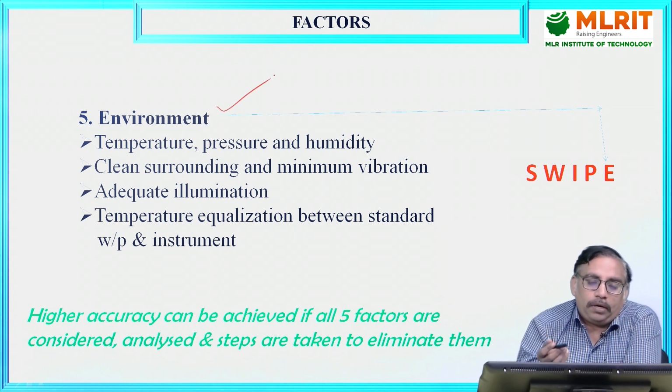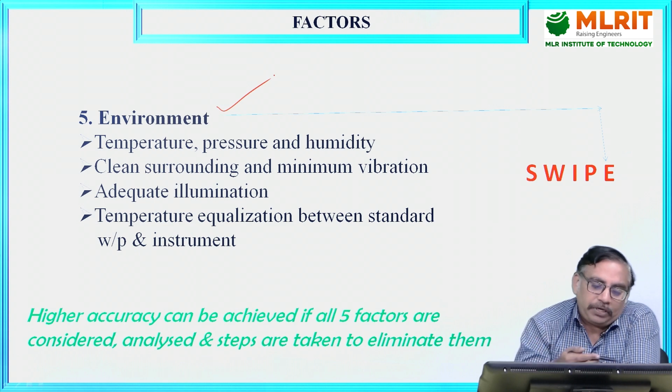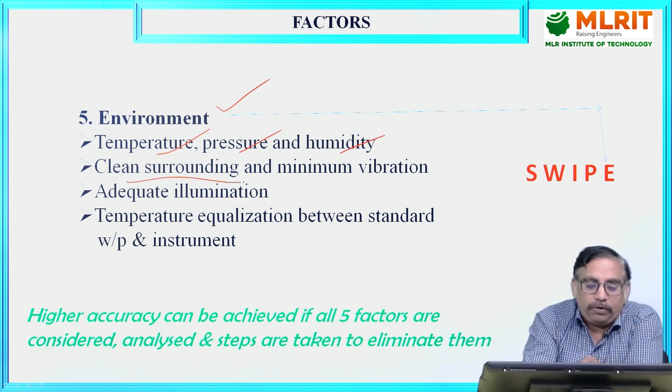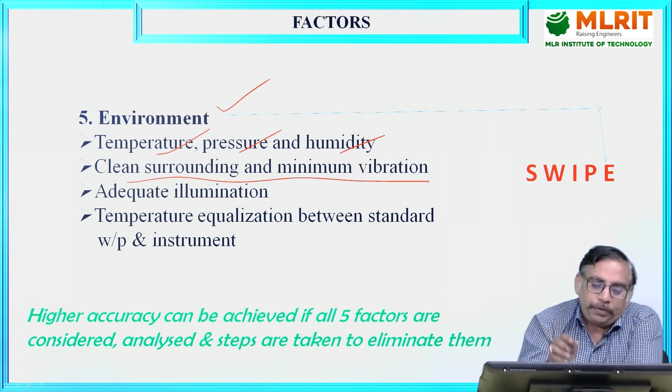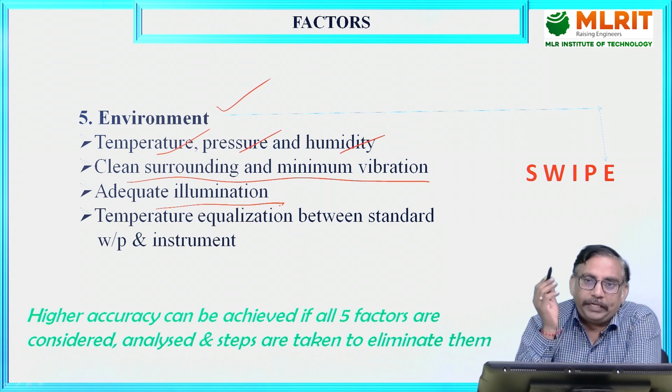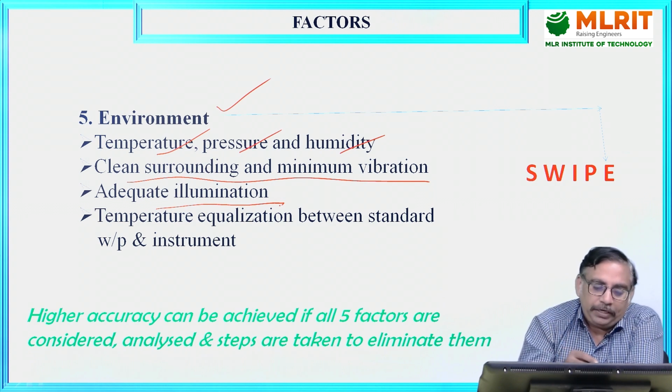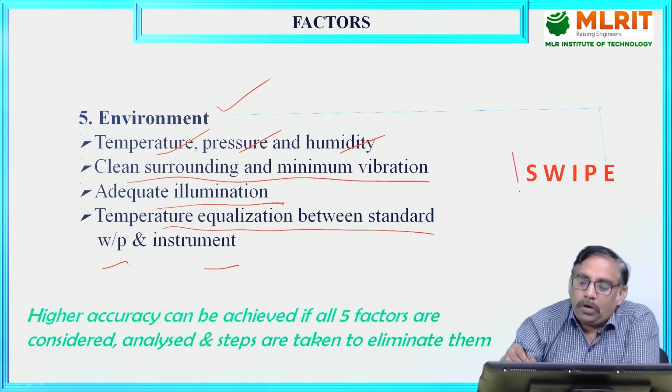All factors of environment like temperature, pressure and humidity will affect the measuring equipment. It should have a clean surrounding and minimum vibration has to be maintained. Adequate illumination, that is lighting, should be there while reading. Temperature equalization between the standard workpiece and instrumentation should be there.